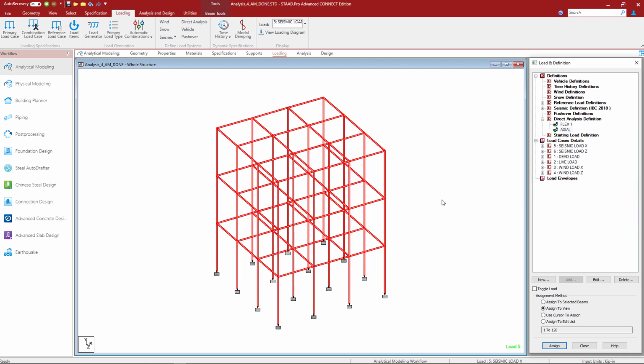Now, as I previously mentioned, for this particular model, I'm going to ask the program to perform an iterative solution to calculate the tau factor. The program will be able to calculate the tau factor, which is also dependent upon the yield strength of steel. So let's go ahead and pause at this moment and consider what yield strength of steel will be used in calculating that tau factor.